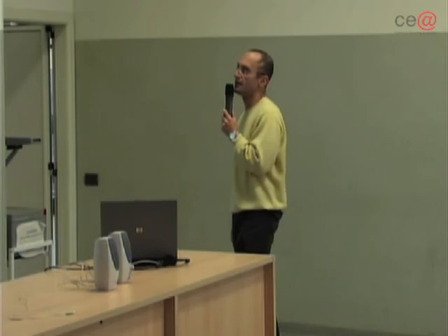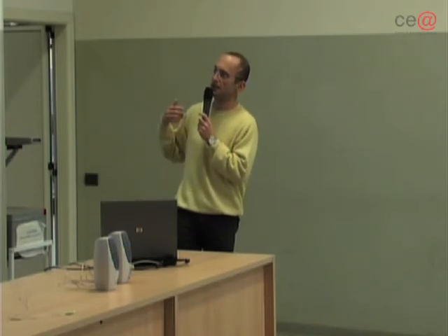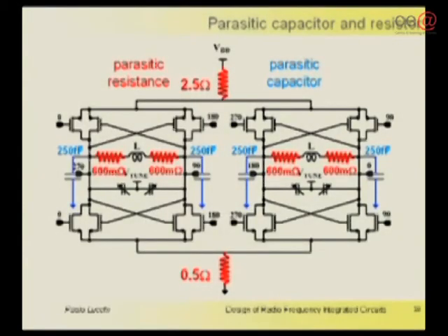And here in blue and red, I have pointed out an estimation of the parasitics that were believed responsible for the differences. So we can see parasitics on the bias line, parasitics on the inductors, and the capacitor parasitics on the two oscillating points of the VCO.